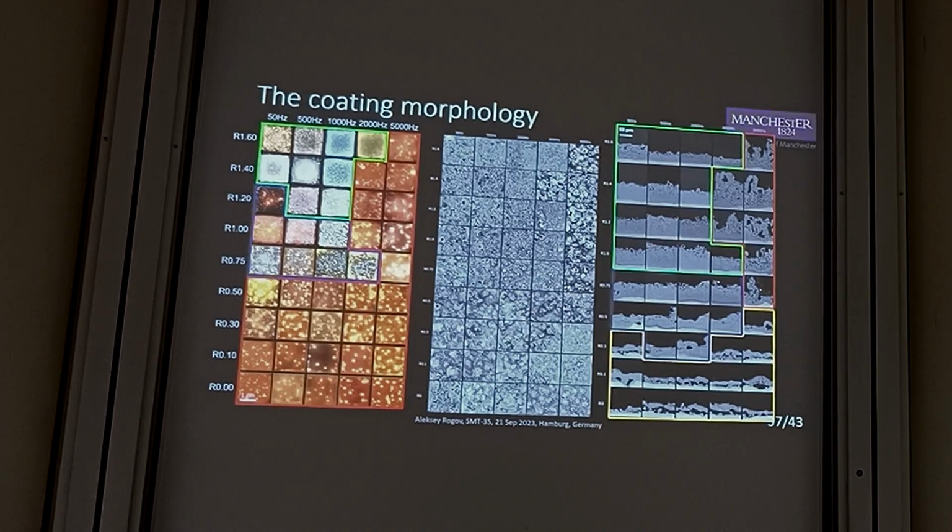So first of all, we can consider how the micro-discharge pattern depends on the frequency and current ratio. Here you can see the final step of the process before its termination. The overall duration of all processes was set to 30 minutes, so you can see the final seconds of the process displayed here. And what's interesting is that we have three characteristic regions. First, the largest one, most of this map, looks like arcing or very aggressive localized discharges. The second one is a soft sparking region in the green frame, and